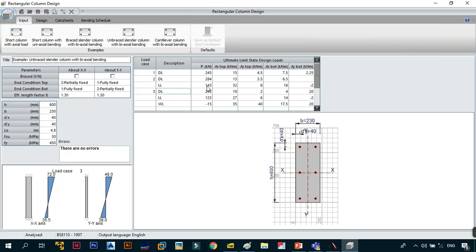You really can't expect to design a column for tension when you're using concrete. But remember, yes, the wind load will be tension because it will try to bring about tension within the column. But as you can see, the loading is quite low. It's not even significant. It's significant in this case that it's going to induce some moment, but then it's very small.